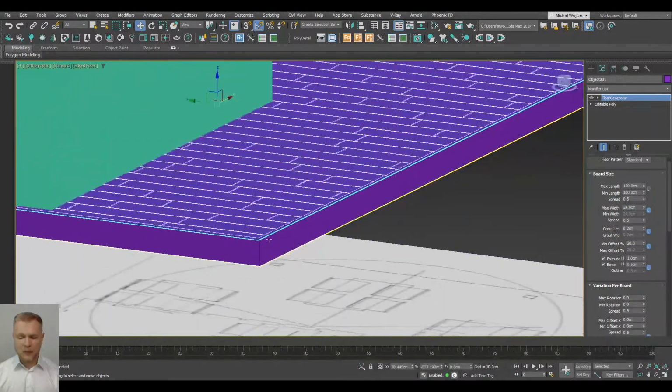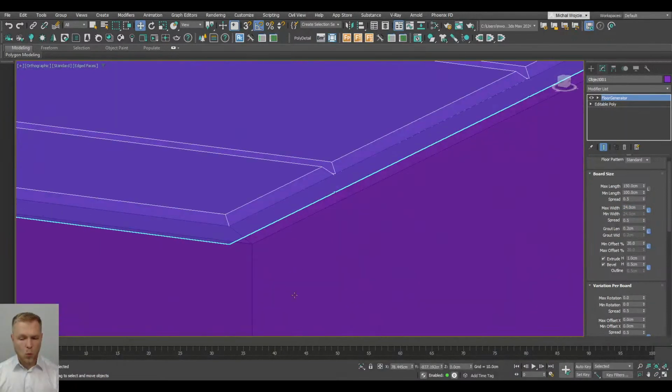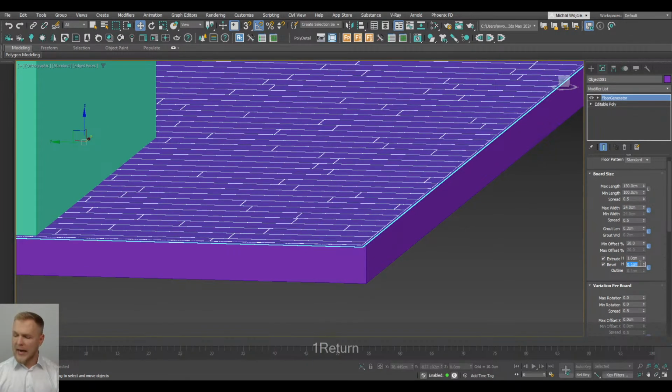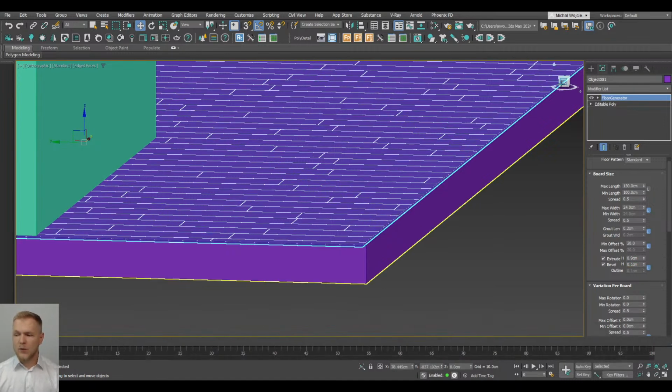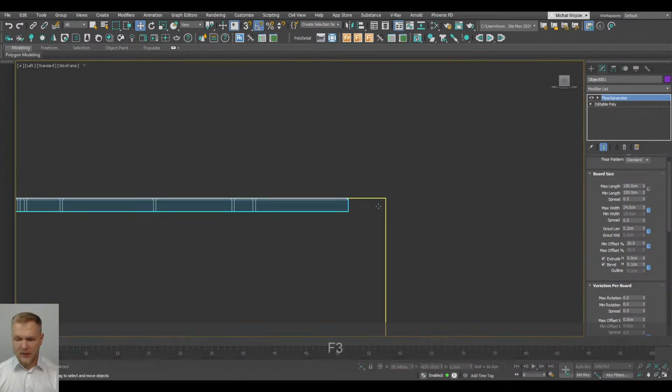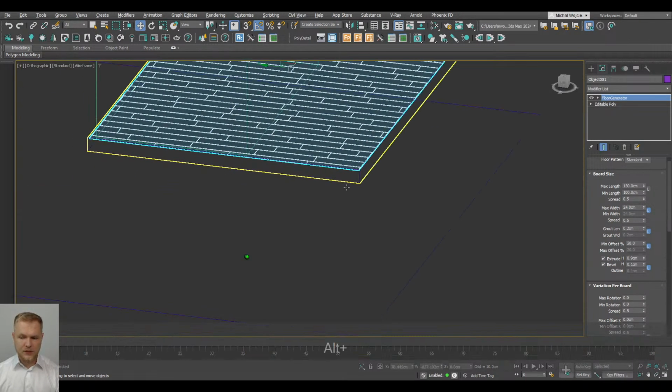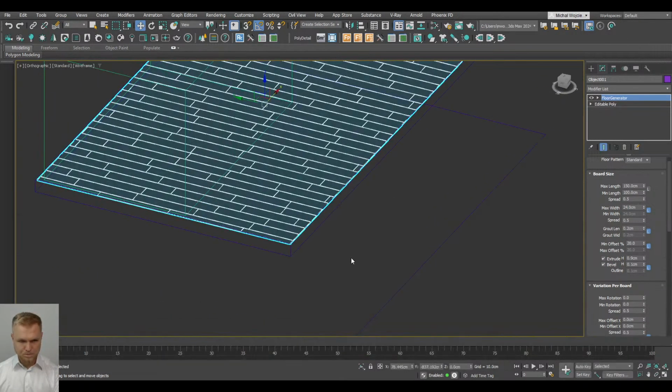Also remember that we went for -1 when we were extruding, so in this case I'm going to go for bevel of 0.1 and extrusion of 0.9. This way, if I'm going to look at this object from a side, this top is going to be perfectly aligned with the borders that we created for this object regardless.